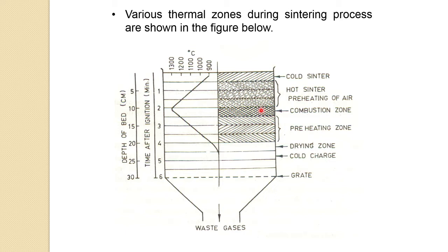Now, whatever air comes out from the combustion zone is quite hot and under suction. Below the combustion zone, all the pellets are green pellets. So, what it does is preheat the green pellets below the combustion zone. Mostly calcination and those things occur here. These are already preheated because the temperature is very high. So, calcination and other things occur in this zone, and as it passes, the pellet gets colder and colder. So, the temperature keeps on dropping.